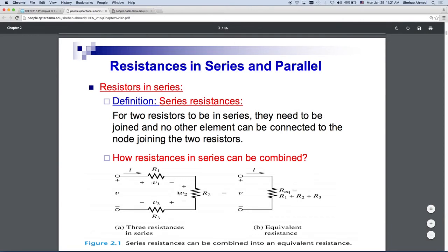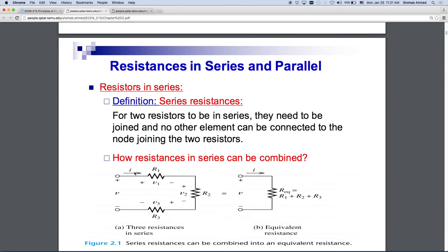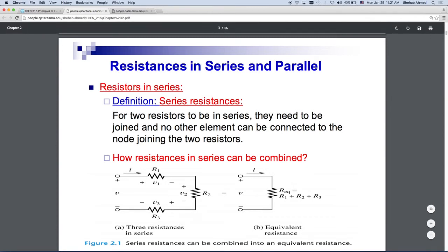If you have 3 resistors in series, as you see here, these resistors will have the same current flowing through them. If you have a line with 3 restrictions, it's the same flow rate through the whole line, except that if you want to maintain the same flow rate, these pressure drops are something you have to oppose and figure out a way to overcome. Resistors in series have the same current flowing through them, but they will have different voltage drops across them.